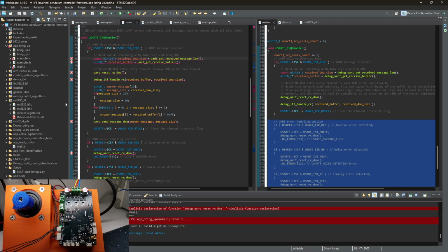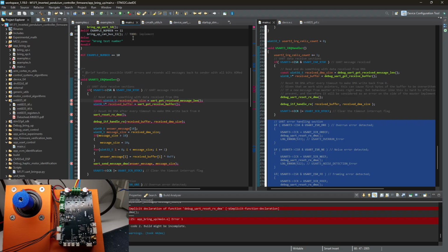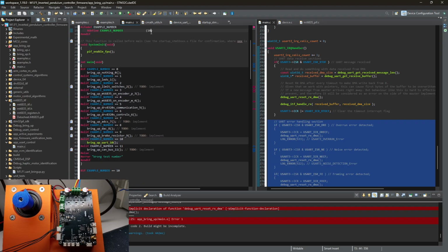I remember the issue because I have a custom-made debug protocol that allows you to save streams of data or buffers of data. Streams are endless and buffers are constant length. And to implement this feature, I had to make a very custom UART setup. And this example expects a standard UART setup. So given that we don't run the standard one, we cannot test it yet until I fix it, and fixing it is not my plan for today.